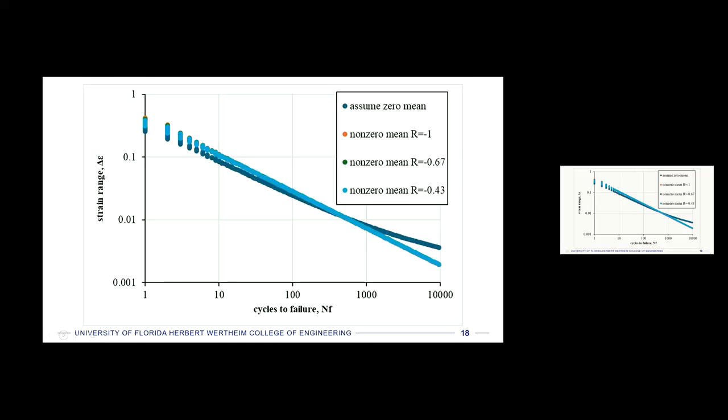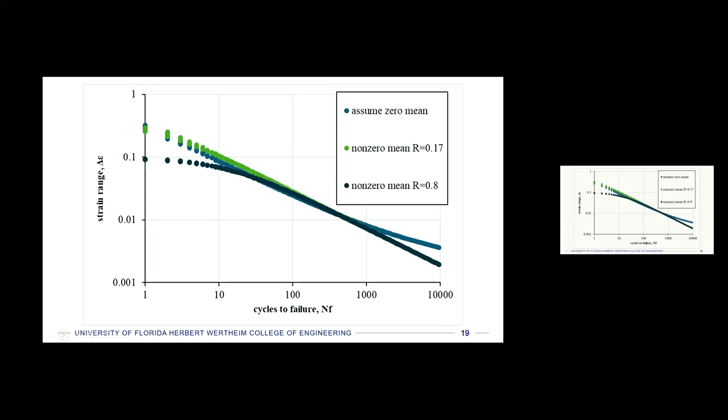And so now the lighter plots on here, those other lines that just showed up, are for stress ratios that are negative. So you have negative to positive, a little bit more fully reversing. And I found that most of those values fall above the values on the other plot. So for the same strain range, we would get more cycles to failure. We get a longer life for a lot of these. We can also do that for the positive stress ratios. I know that I'm 1 minute over time. We can see that it has a similar trend, except when we get to these really high values here. Then we get a drop in life, not an extension of life.